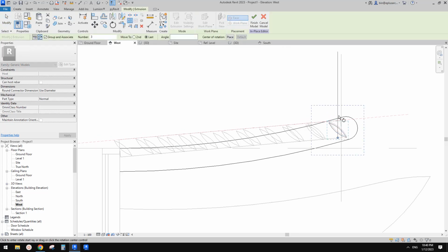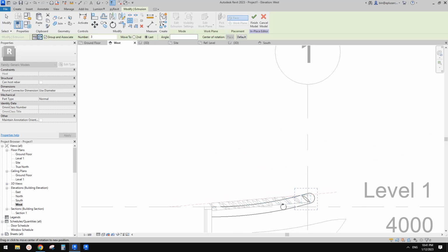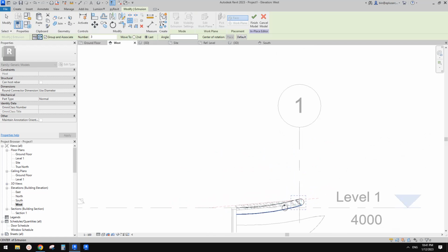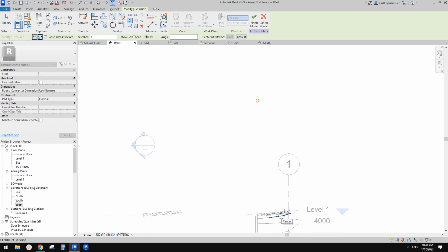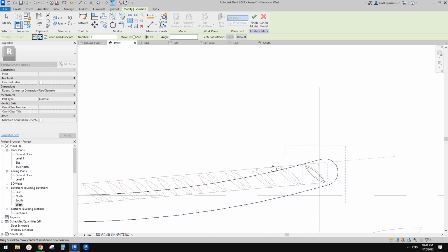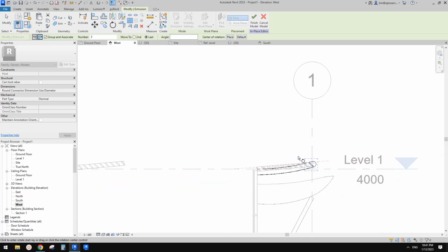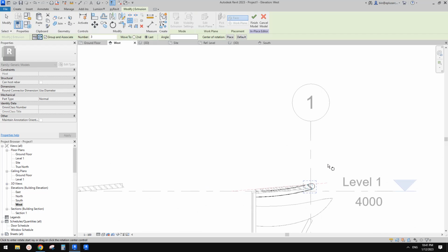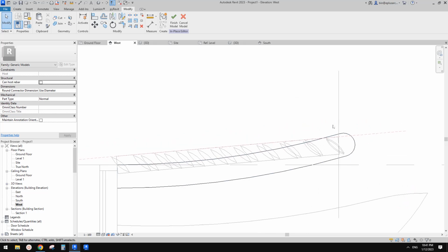So use AR and use radial, space, type SC to snap the center point. So you can see it will be there. Where is it? Yeah, over there. So as long as you type SC and pick this edge, that will be correct. And then, did I? Sorry, I forgot to press spacebar. So let's just do it again.